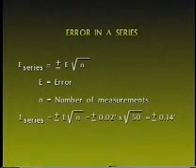Using a similar technique for each of the 50 tape lengths in a 5,000-foot distance will produce an error of plus or minus 0.14 feet. This answer illustrates that random errors tend to be compensating. If each tape length definitely contained 0.02 feet of error, then the total error in 5,000 feet would be 1 foot.